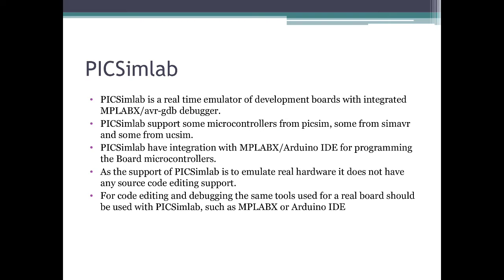Now we will go to PICSIMLAB. PICSIMLAB is a real-time emulator of development boards with integrated MPLABX debugger. PICSIMLAB supports some microcontrollers from PICSIM, some from SimAVR and some from UCSim. PICSIMLAB has integration with MPLABX and Arduino IDE for programming the board microcontrollers.